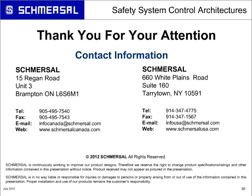So when you look at their specs on the safety circuit, they'll give you examples. This is what you have to do to achieve a Category 0 stop and control Category 3, performance level D for your safety system. If you want to achieve a Category 1 stop, this is what you do. So you really got to refer back to the manufacturer of that particular drive. To me, I think it's too difficult to make a blanket statement on whether you can or cannot without consulting the drive manufacturer.